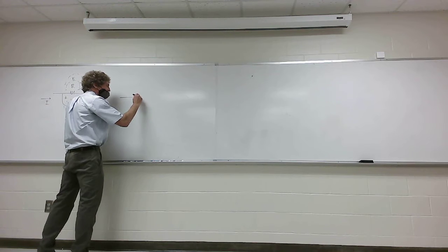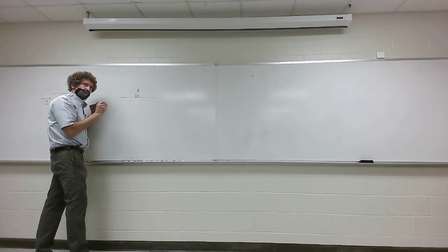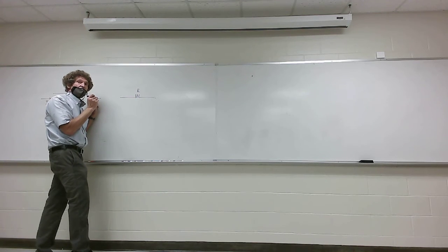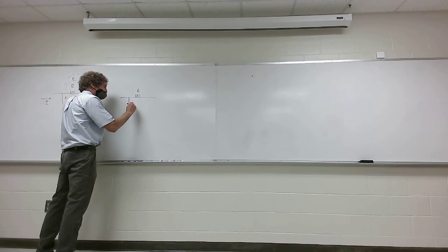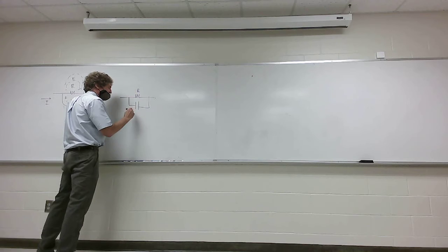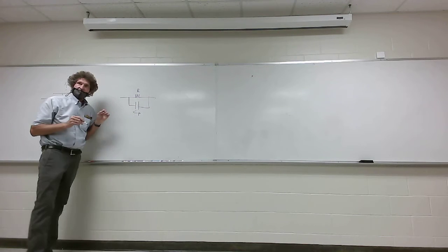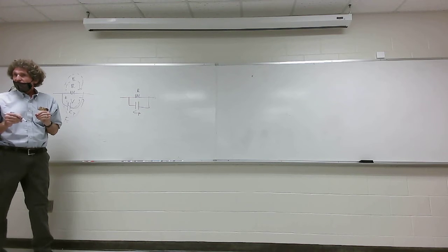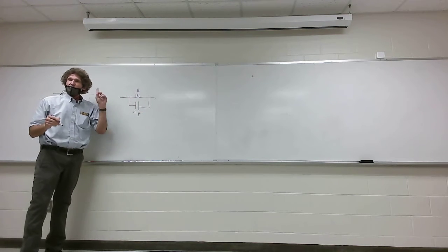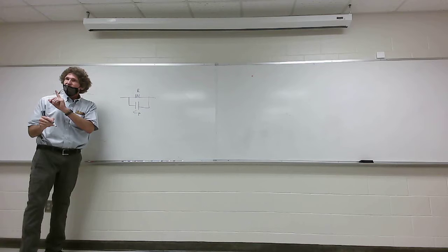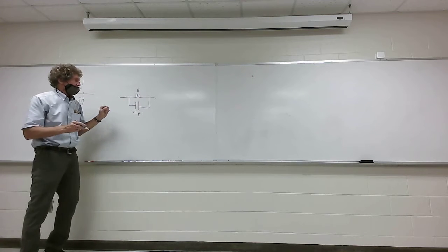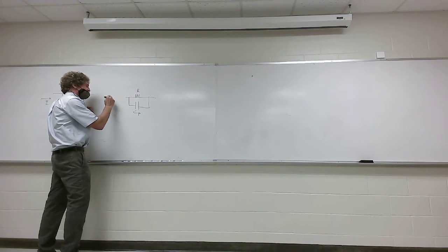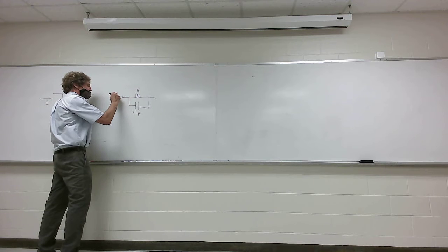Always start with the element itself. That's what it'll look like at low frequencies. Now, anything I put in there can't alter the way it looks at low frequencies. Keep that in mind. Now I'm going to put a small capacitor here, and that's parasitic. That's what that sub P means. It's unwanted, but it's inevitable. And then, because of mainly the length of these wires, keep this in mind, the length of the leads is critical, you get an inductance like this. L, and call it L lead.